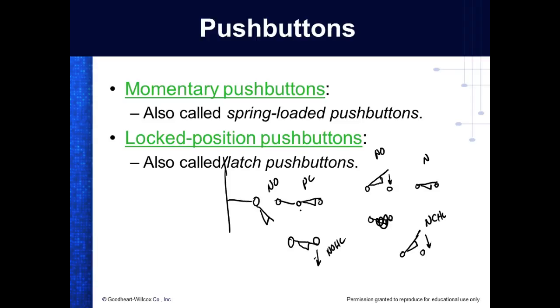The number of switches, or contacts, would be the number of poles. The number of positions that switch can be put in that controls a circuit is the number of what? Throws. So if I come over and do this, what's that? Single pole, single throw, because the open is not putting current to a circuit. If I came over here and did this, single pole, double throw. One switch, we can control 2 circuits.